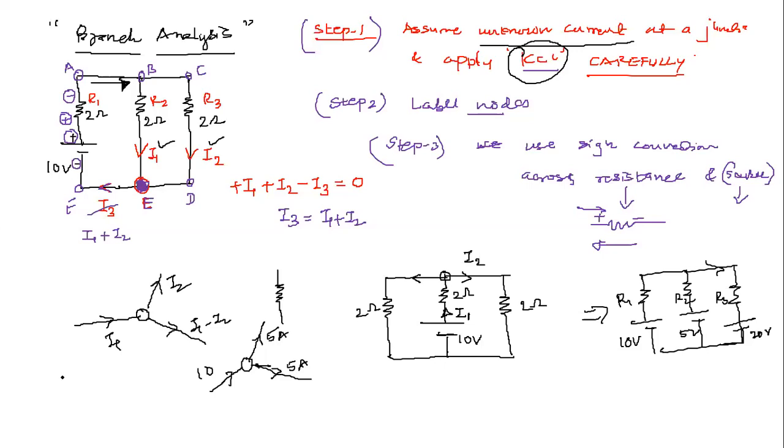So what do you mean by that? See, if you put a plus sign over here, you will get a wrong answer. Because what KCL says for this given junction is I1 plus I1, right? What do I write for this? Minus I2, and it is going away from it, right? So I need to put minus I1 minus I2. Now, what will happen when I solve this? You are going to get a 0. See, this gets cancelled out, right? It's going to get 0.